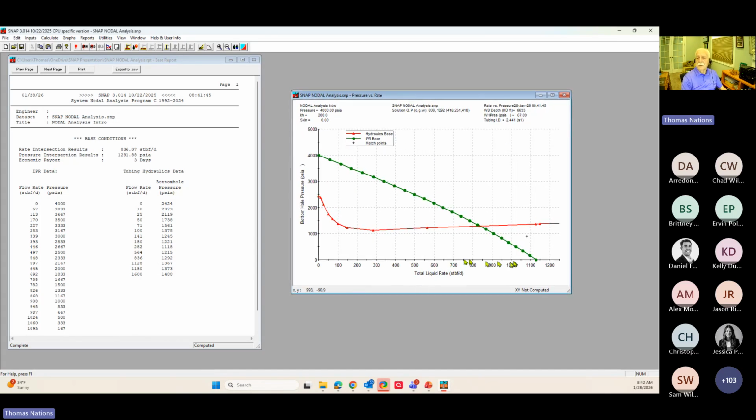The other thing about graphs is the scales on the graph. You double click on the X or Y axes, and you can manipulate the chart X or Y axis. There is an automated way to do this, an undocumented feature, by the way. If you hold the Shift key down and float your cursor along the axis you wish to change, I'm holding my Shift key down right now, I'm going to double click here.